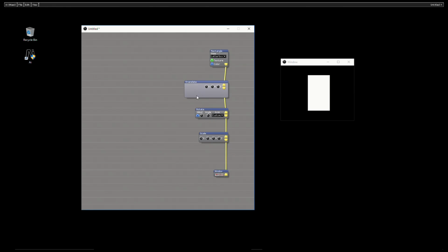Now, if I right-click and I show parameter, I want to expose these three modification amounts, and on the ports, I want to expose the modification port. Now, this will allow us to have separate X, Y, and Z modification. However, I could also use a vector input, so that would allow me to specify the numbers, like we saw with the colour. Our position, X, Y, and Z, is actually three numbers making that overall value. So that's what I'm going to do, in fact. I'm going to choose the vector in.